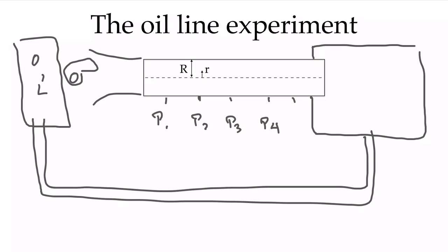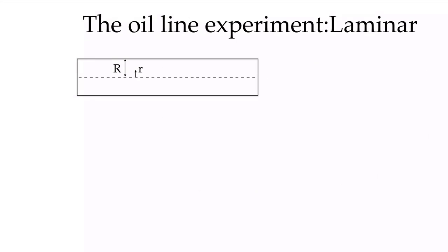We put a small pin in here so that we can disturb the flow, and we can pull this pin in or out in order to make contact with the flow or not. And we do that in order to trigger turbulence when we want to have turbulence. We'll talk about that as we talk about the laminar flow.